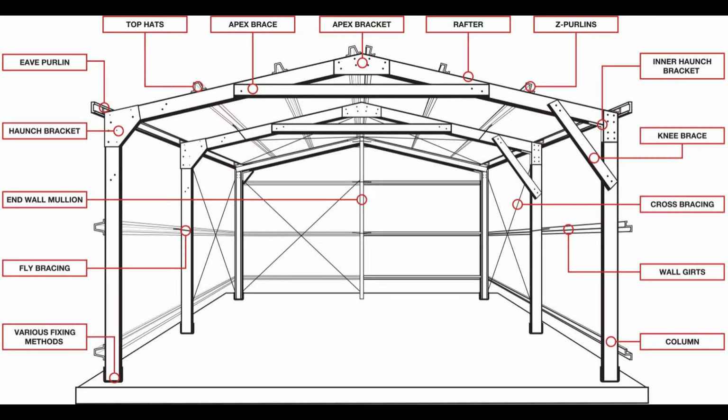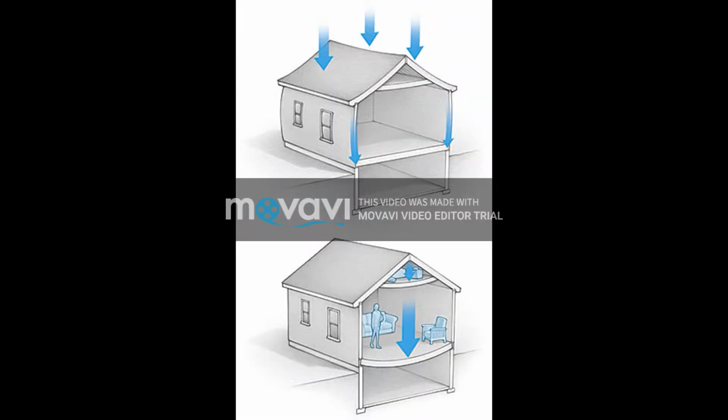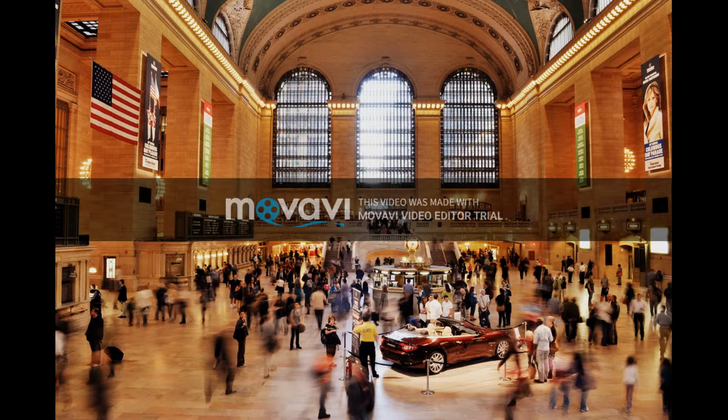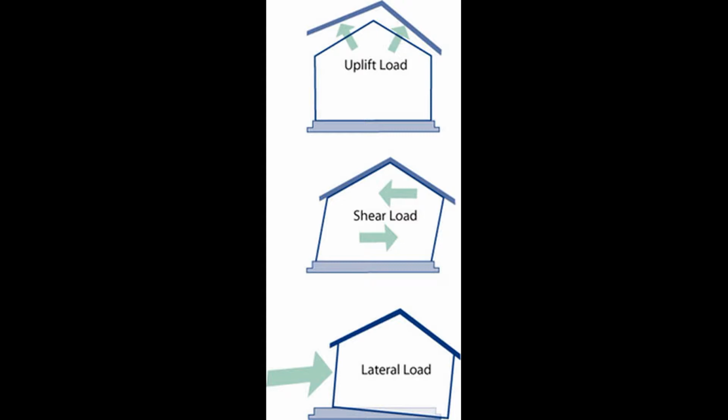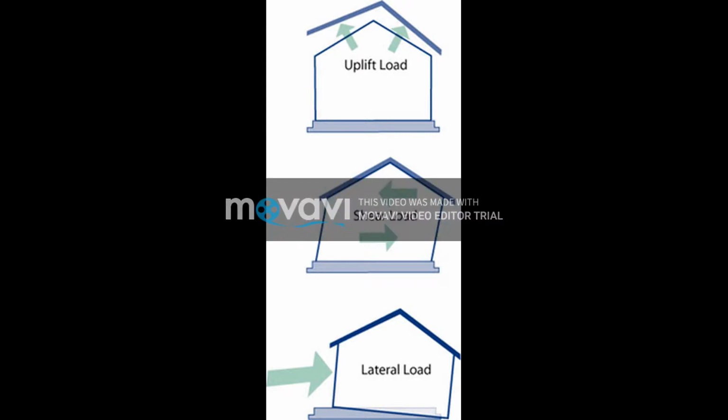When designing a domestic shed, there are many sectors of the design process which must be assessed correctly. This includes calculating the three main types of loads which have a major impact on the structure of a shed: the live load, which is the occupants of the building, which doesn't necessarily have a great impact, as well as the other two loads, dead load and wind load. Wind loads are extremely important as they impose suction and compression loads on the structure. These loads must be taken into strict consideration as they will determine the strength of the building.